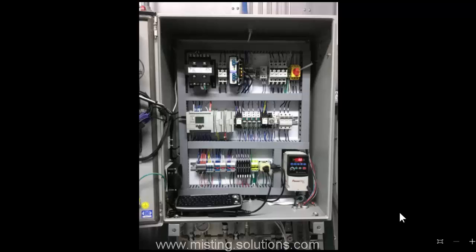Now let's go back to the 0 to 10 volts DC input to the microcontroller and talk about that for a while. That is the heart of what makes a lot of complex stuff happen. That 0 to 10 volts is a constant live signal within this microcontroller. But that does not mean the humidification supply output, the humidity output, is tracking that 0 to 10 volt signal all the time. There is a time delay built into it.